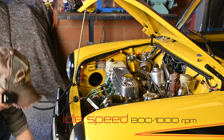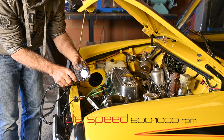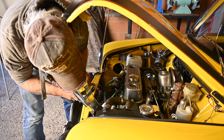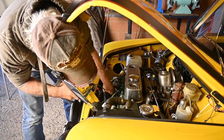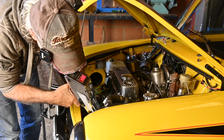Alright, so now I will use my flashlight and you will see the flashes. You see that? And I'm going to shine inside the engine and see where I am. I'm going to adjust my distributor by rotating it until I have the right amount of degrees. 8, 9 degrees advance. So for me that is good. I'm going to keep it that way.